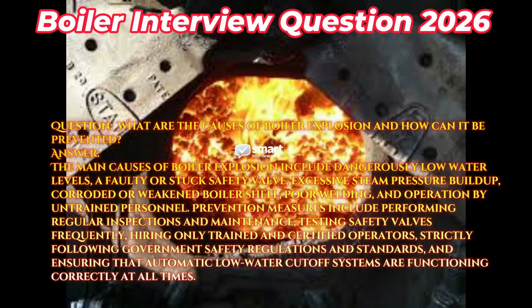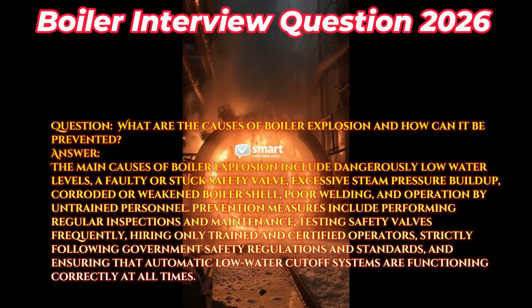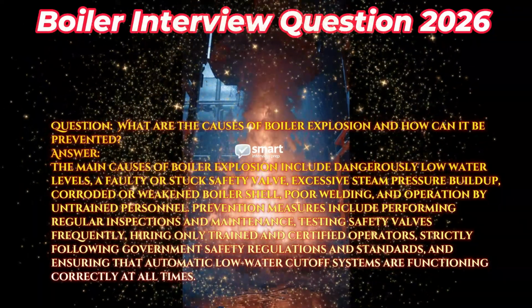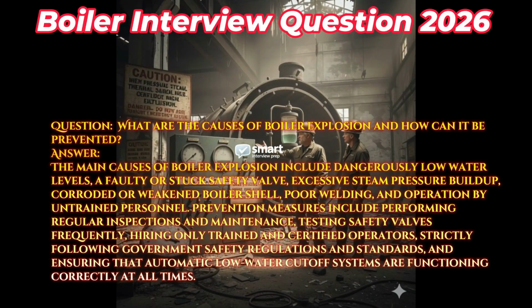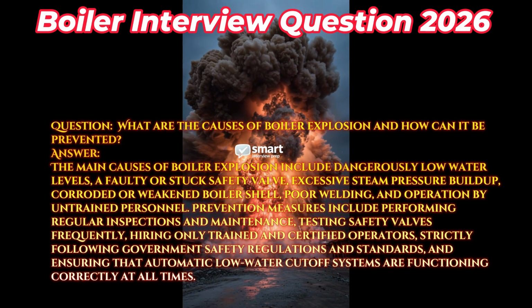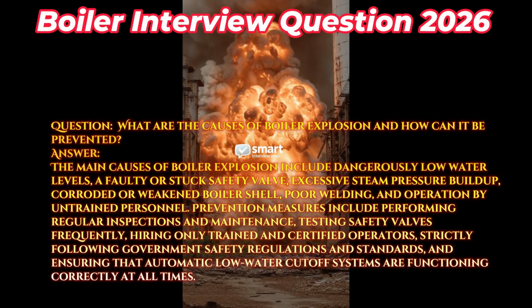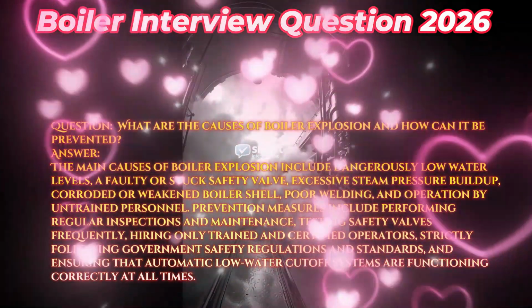Question: what are the causes of boiler explosion and how can it be prevented? Answer: the main causes of boiler explosion include dangerously low water levels, a faulty or stuck safety valve, excessive steam pressure buildup, corroded or weakened boiler shell, poor welding, and operation by untrained personnel. Prevention measures include performing regular inspections and maintenance, testing safety valves frequently, hiring only trained and certified operators, strictly following government safety regulations and standards, and ensuring that automatic low-water cutoff systems are functioning correctly at all times.